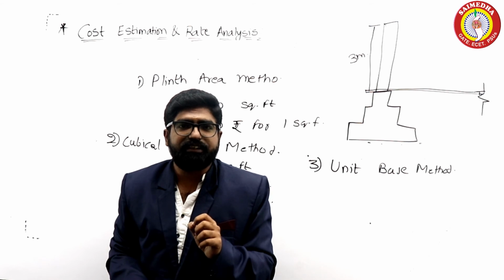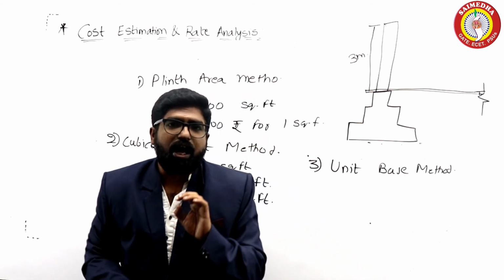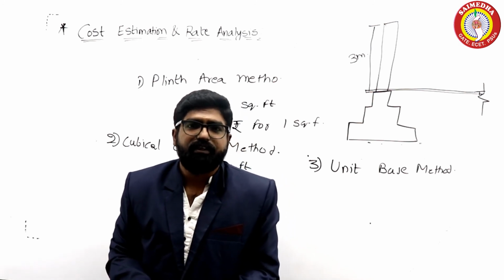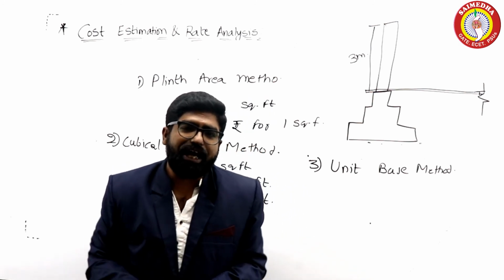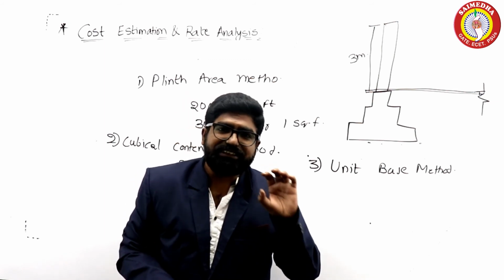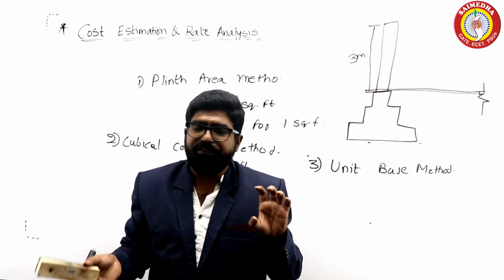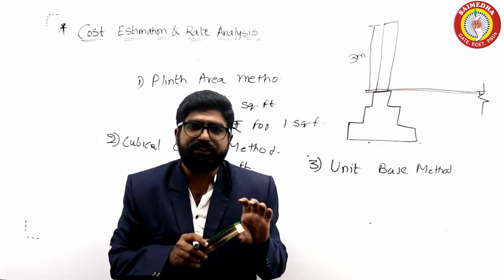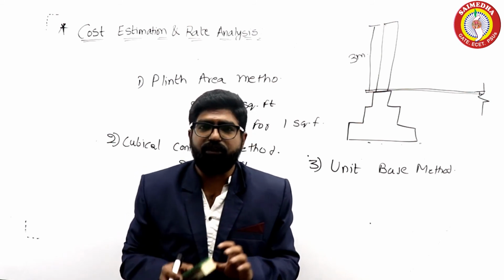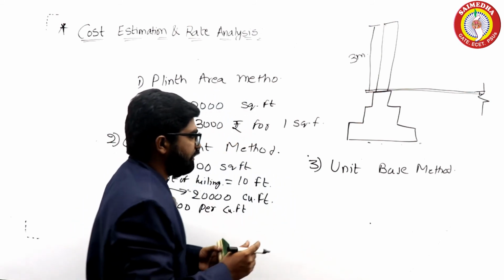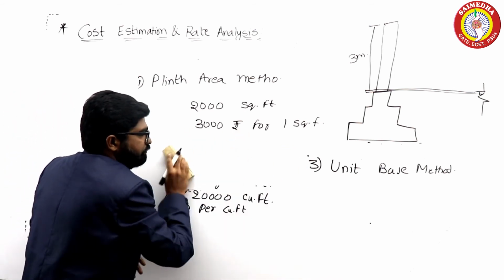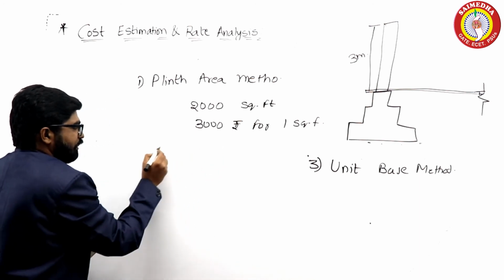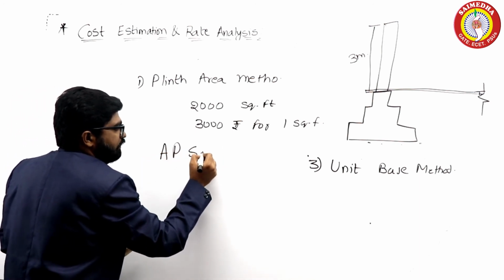So what is schedule of rates? Now, do you know how much a labor costs per day in Hyderabad? Maybe you know it, but what happens is you need to take a standard rate for it and compare with it. Is that higher or lower? So where is your standard rate present? Your standard rate is present in the schedule of rates. There are different schedules of rates. I'm writing it here. If you are working on a state board project, then you will use the AP schedule of rates.